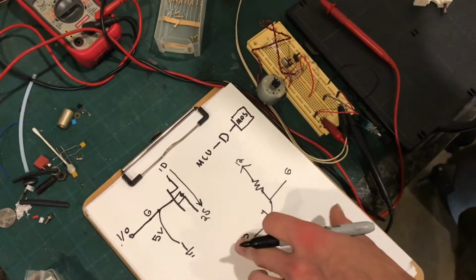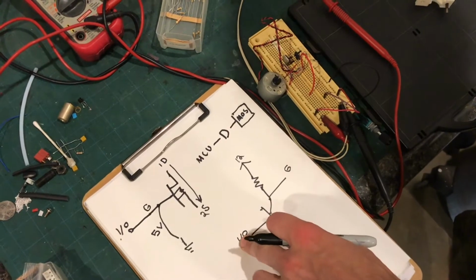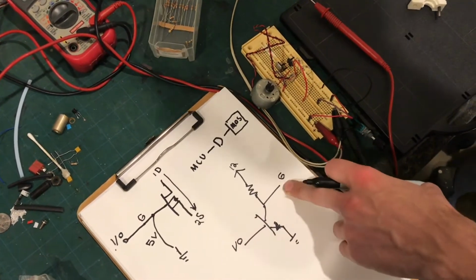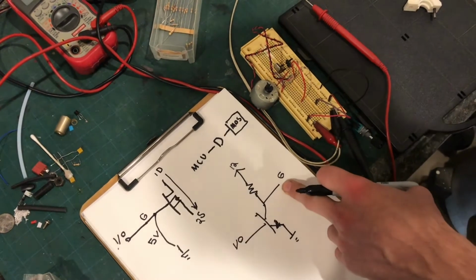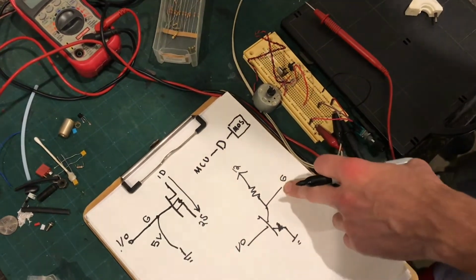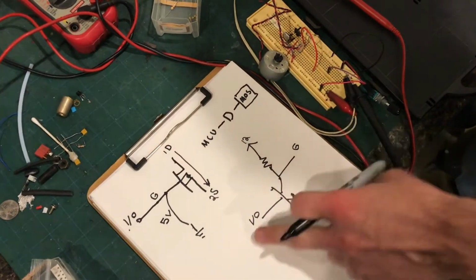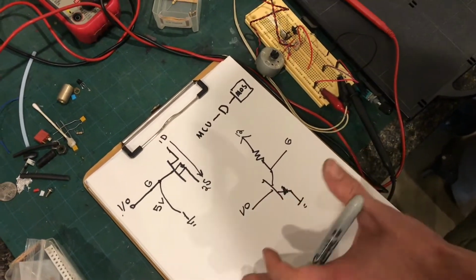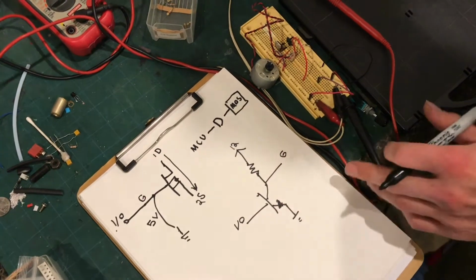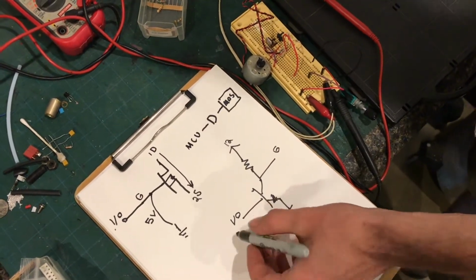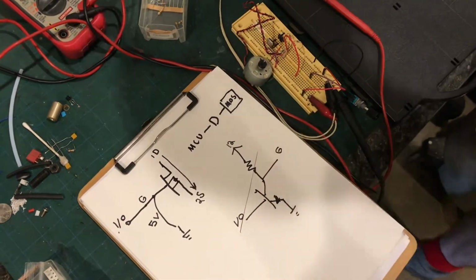The problem with this is that when the I/O pin is on, the gate is off, and that inverts the logic. Unless you're going to do a software update to change that in the microcontroller program, which you definitely can do, but I wanted something that was not inverting. So I'm going to try another one.